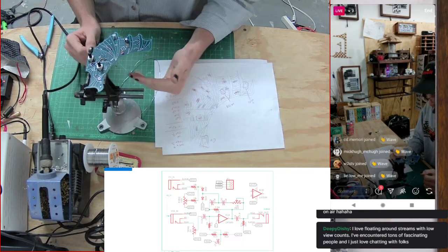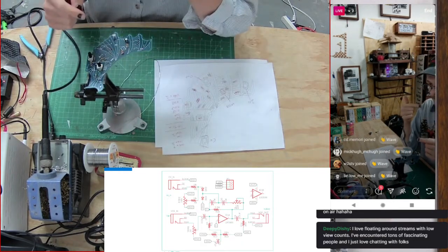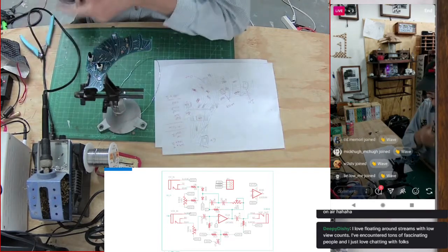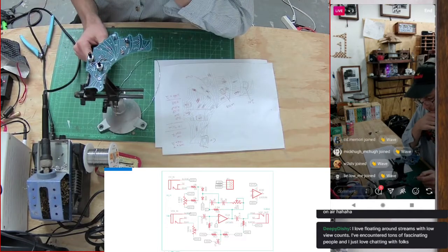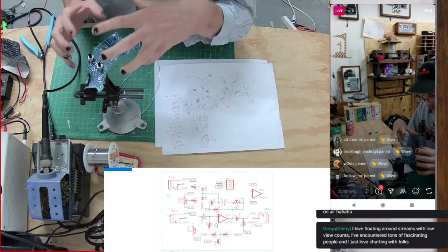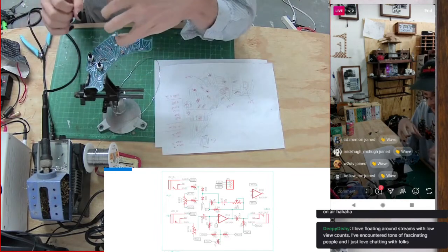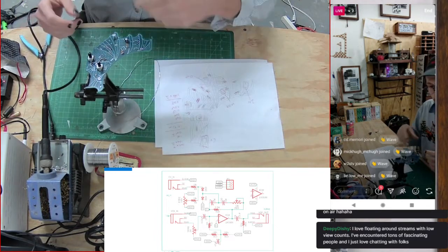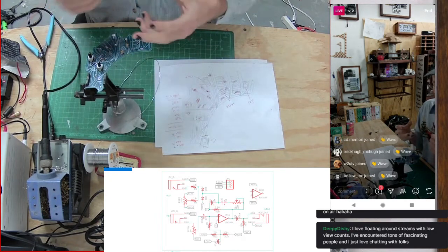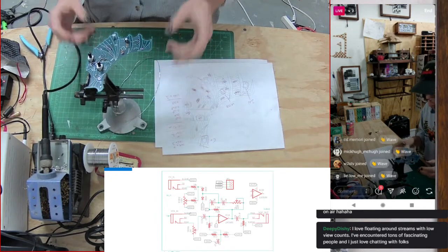In this case, there's a little bit of feedback coming back into the filter, which lets it be slightly amplified, and the resonance controls how much of that feedback goes in. It gives a really nice squeaky, squelchy, harmonic feature to our filter, which I really like.